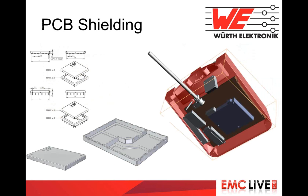Now we go to the PCB shielding. In the introduction, I said that when we know exactly where a noise source or a sensitive part of our circuit is, it's more efficient and also cheaper to go there and just shield this critical part. For this kind of shielding, you can use conductive enclosures, small boxes called PCB shields. You can customize them to fit exactly the part of your circuit that you want to shield and place them with different technologies.